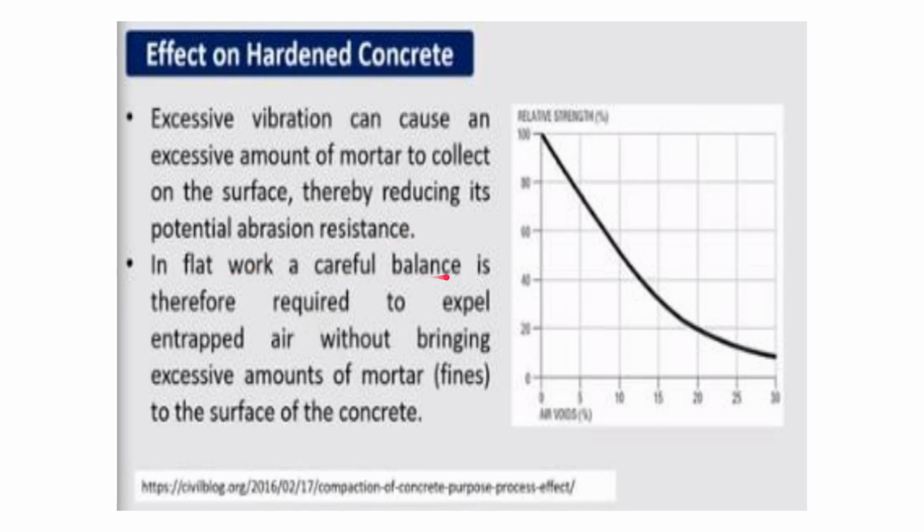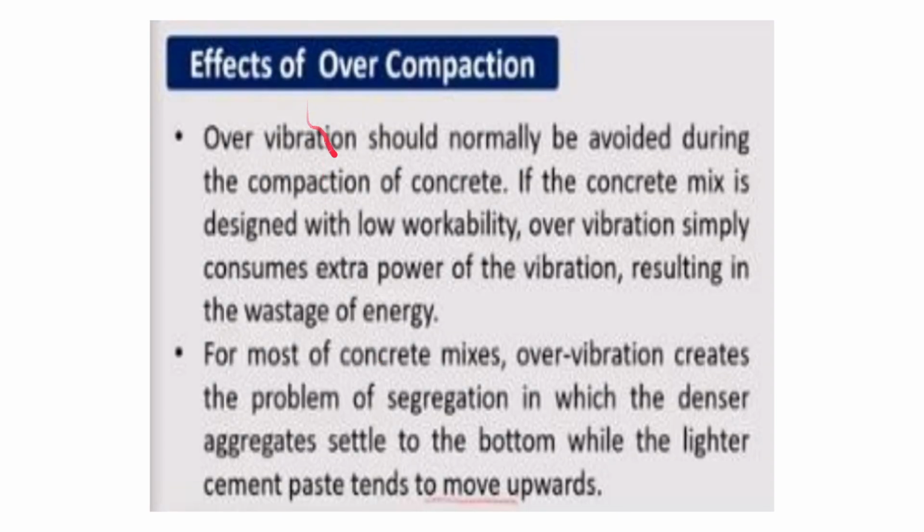And in flat work, a careful balance is therefore required to expel entrapped air without bringing excessive amounts of mortar fines to the surface of the concrete. So we need to expel the entrapped air, but we also don't want to bring excessive amounts of mortar fines to the surface. Okay, so it should not be less, it should not be high, it should be in between. So now let us see what the effects of over compaction are.